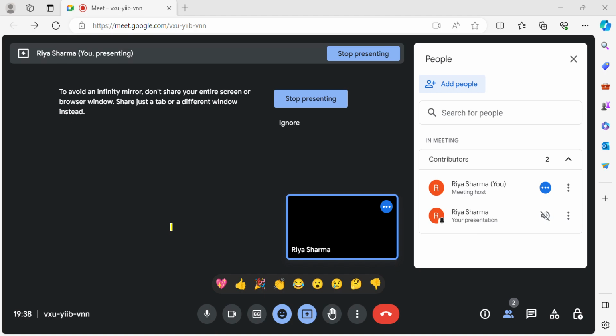Okay, so the answer to it is 100. Let's solve this problem. As we know, Cp minus Cv is equal to R, so Cp is equal to R plus Cv. So what will be Cp? 0.3 plus 0.7, because R equal to 0.3 kilojoule has been given here. Always check the units: kilojoule per kg Kelvin, 0.3 plus 0.7. So this is 1 kilojoule per kg Kelvin.